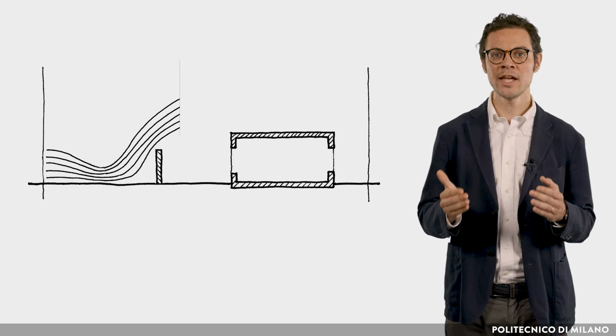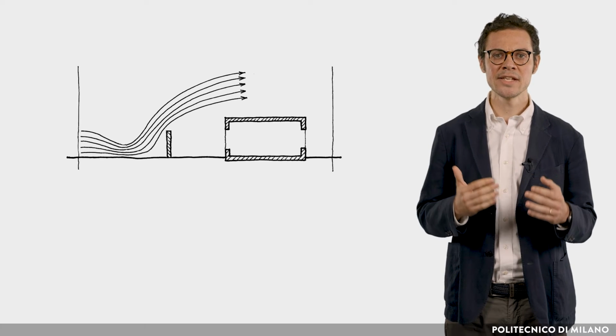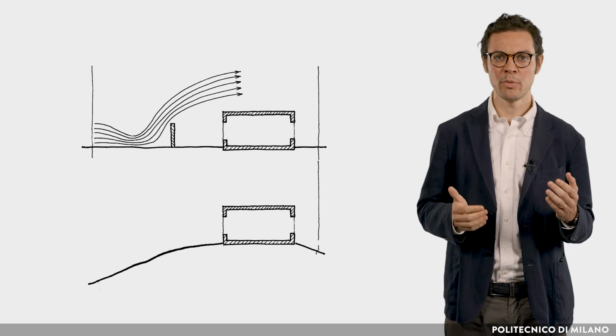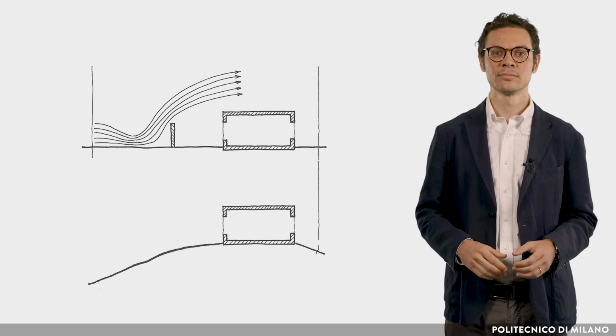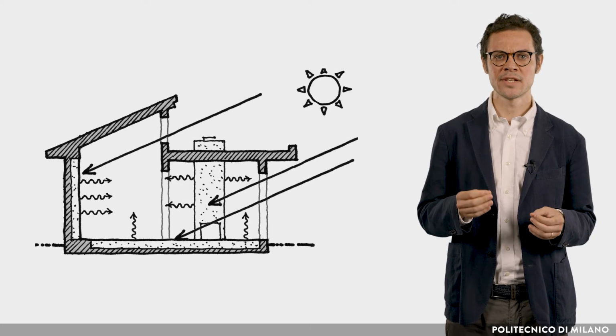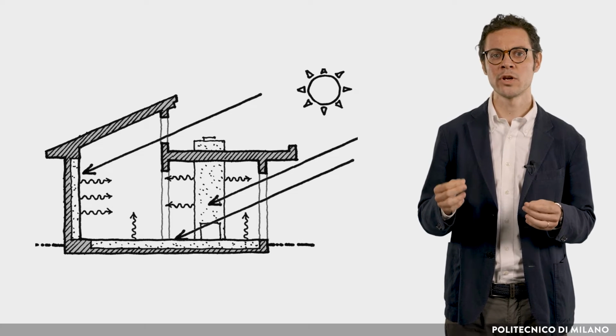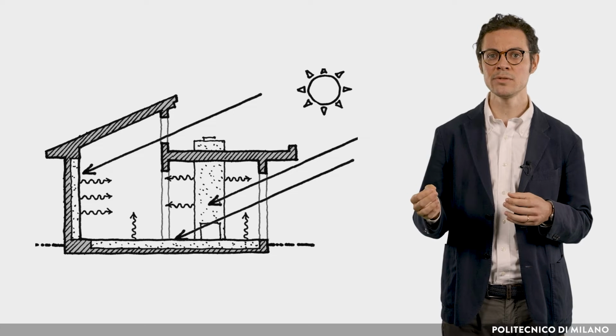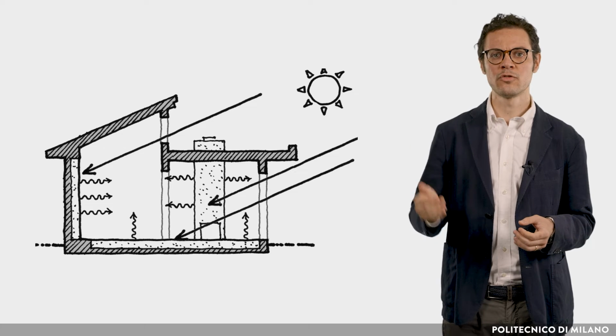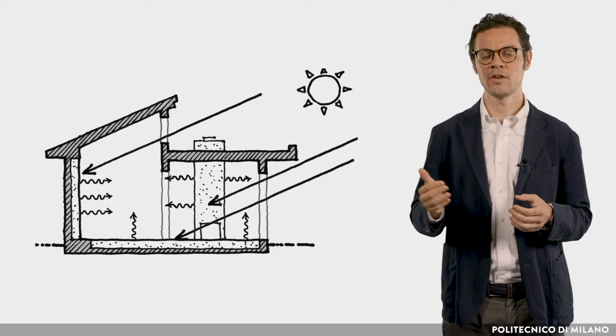Generally, in such climates, building sites should be so selected as to provide shelter against prevailing winds and cold air pockets in ground depression. Buildings should have their main glazed elevations oriented north-south, also northeast-southwest orientation is appropriate. With carefully calculated sun shading, this orientation will allow a certain amount of solar heat to penetrate during the cold season in the early morning and to cut off low west sun in the afternoon.